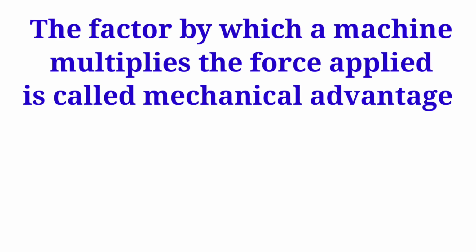Now, mechanical advantage of a machine. The factor by which a machine multiplies the force applied is called mechanical advantage. The force applied on the machine to do some work is called effort. The force applied by the machine on the object is called the load. So, mechanical advantage MA equals load by effort.